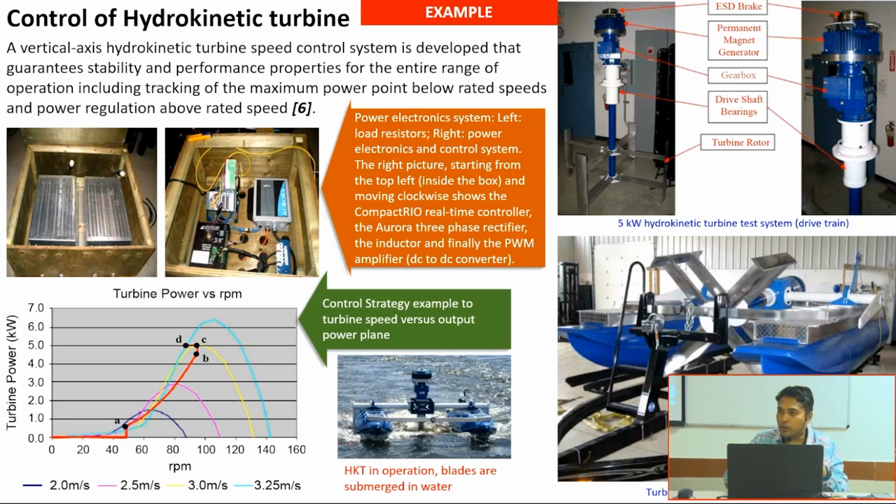Now this floating device can be anchored through some mooring, either from the riverbed or from the bank of the river. This floating device has been given because they do not wish to depend on the water level. So if the water level goes down, the whole system goes down, and if the water level goes up, the whole system goes up. So this is another modification.